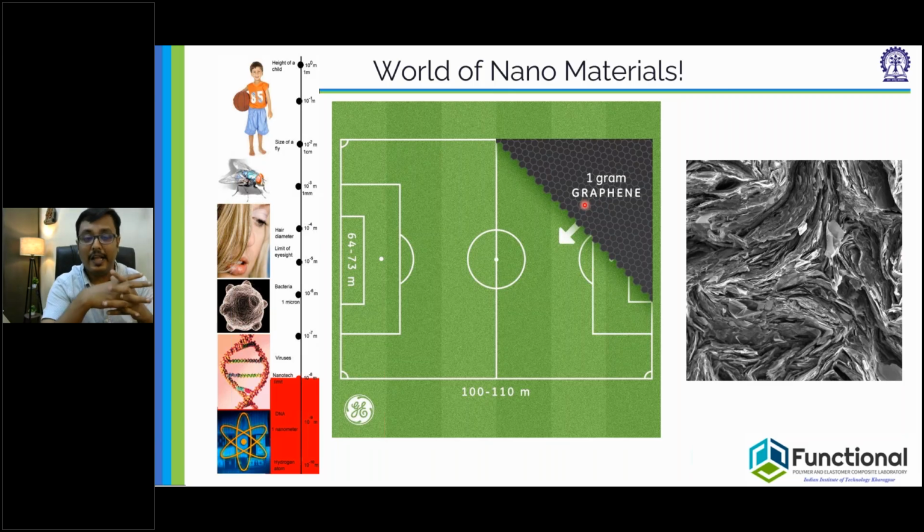Now, these nanomaterials, due to their unique shape and size, demonstrate unique properties like strength, barrier property, electrical property, and electronic properties that are quite different from the traditional macrofillers. So that's what brings novelty to the composition when you mix this nanomaterial into any polymer. That means at a very low dosage, you can achieve good performance compared to the macro composite, in which you put big size fillers and achieve the properties.